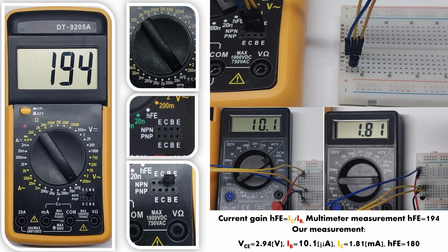Discrepancy between direct measurement on the multimeter, and our own testing, is due to losses in DuPont wires, connectors, and probes. The same principle applies for testing a PNP transistor. Just be sure to properly identify and orient terminals, and choose the appropriate slot on the hFE port on the multimeter of your choice.